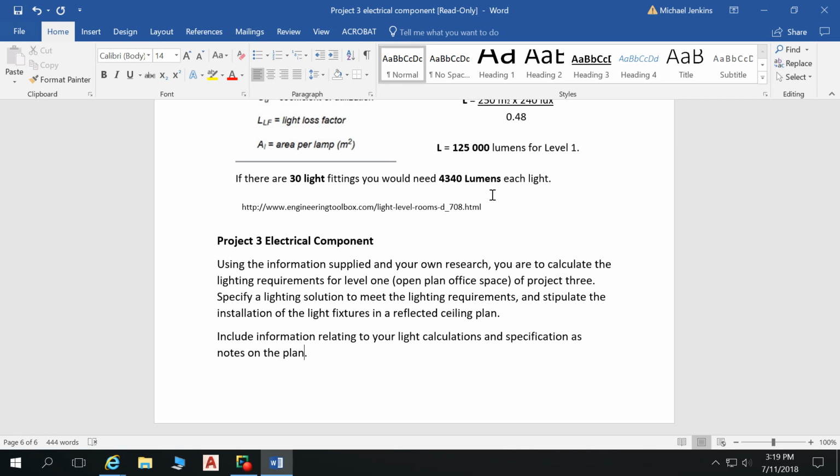Cool. And if you're going to go with a suspended grid type ceiling system, like a Rondo acoustic tile ceiling system, I'm not sure how you go about drawing that up in Revit. Possibly there are some ways in Revit to go drawing it up. How I would do that in AutoCAD though is to just get my internal walls, choose this wall, and then offset by 600, and then get my first grid point, and then offset that by 20 millimeters for my hangers for the acoustic tiles, and then copy that across, and in 30 seconds or so you've got a grid set out for your acoustic tiles for your ceiling.